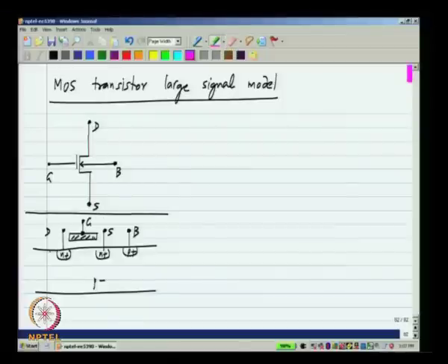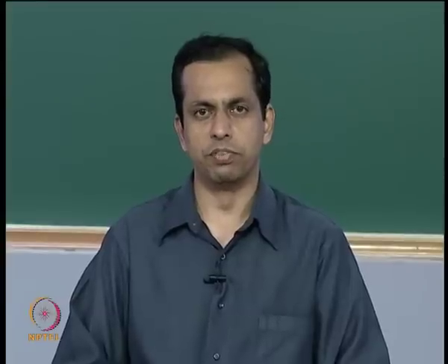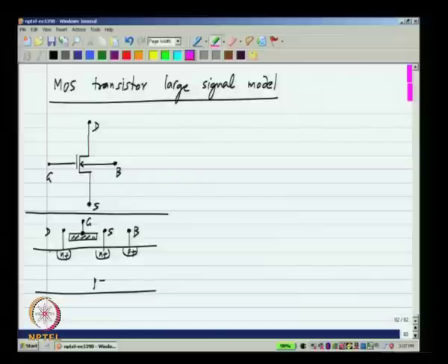It is not our goal here to discuss in detail the physics of the MOS transistor. We will only study the models to a sufficient extent that we can use them for circuit design. Now, one thing you will observe is that from the layout as well as from the symbol, the drain and source are interchangeable. Okay. The device is symmetrical with respect to drain and source, and that is true in reality. We do label one of them the drain and the other one the source, and what makes the distinction is which voltage is higher. Okay. It is not related to how the device is fabricated.